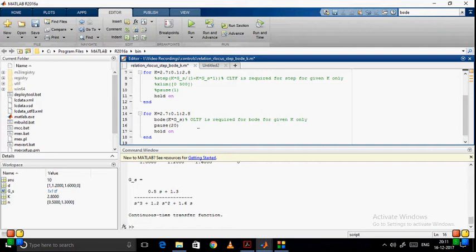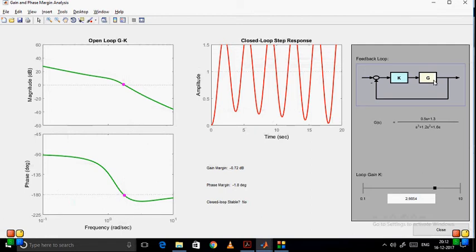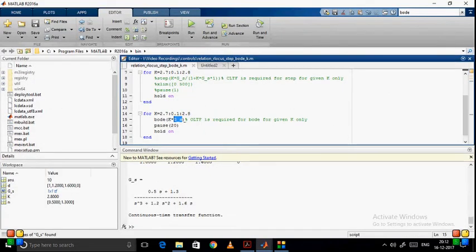Okay. So I am interested in finding out whether the system is stable or unstable, and more importantly at k equal to 2.7 whether the system is stable. So I just have to multiply k into g of s again for a given value of k. G of s is assuming that k equal to 1. But if I want it at k equal to a certain value, I have to multiply that k. My open loop transfer function will be k times g of s into 1, of course, because there is a feedback.